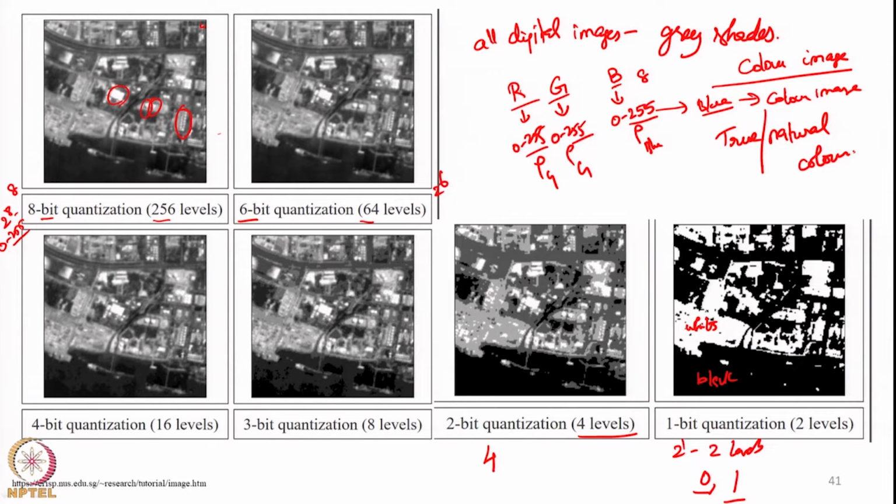In remote sensing, it is also possible to form images with what is known as false color. We can take images in different bands, NIR band, SWIR band, thermal band and so on. Thermal we can leave, and talk only about the reflectance bands, NIR, SWIR and so on. We cannot see NIR directly, so that image will be different shades of grey. We can give some color to it, say different shades of red, and data acquired in the red band we can give different shades of green and so on. This is what is called a false color composite.